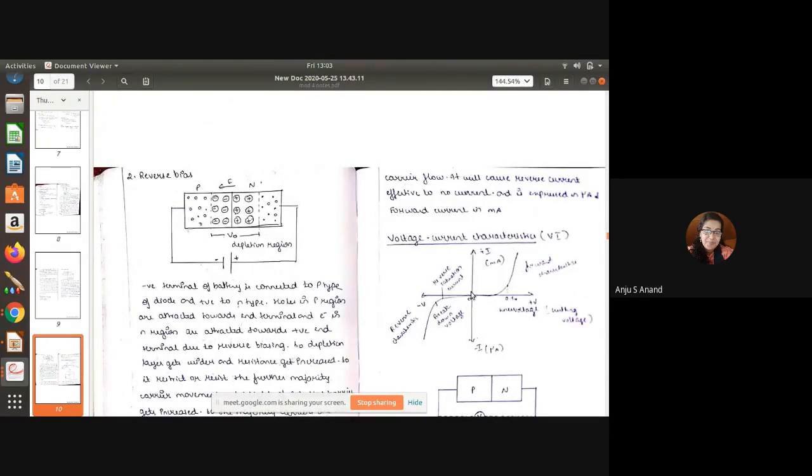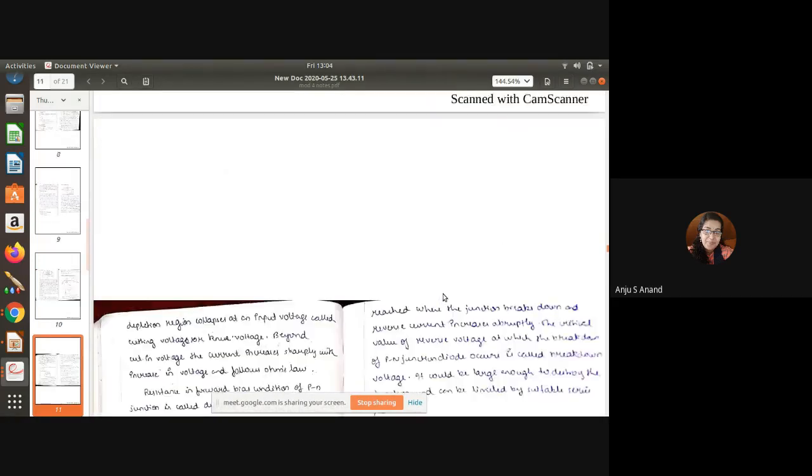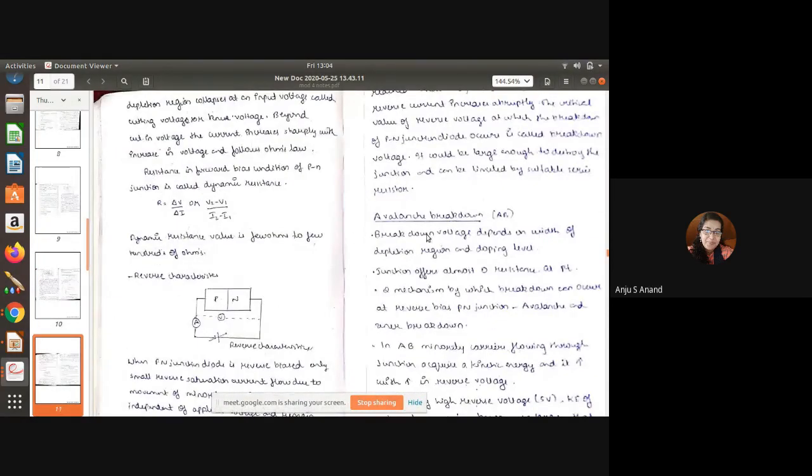The reverse bias characteristics come in this graph, in this negative voltage region. In the negative voltage region, we can see here the breakdown voltage. That is, at a particular negative voltage or reverse bias condition, the current will be enhanced, the reverse saturation current gets enhanced. And what do you mean by avalanche breakdown process?